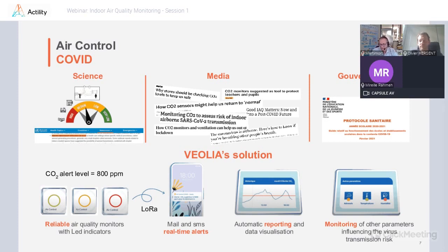So for the position of the CO2 sensor in a room, it depends on different parameters. The objective of this measurement is to represent the presence of the occupant. So if we have 1, 2, or 10 persons in the room, this CO2 can detect, not directly the number, but the CO2 level in the breathing zone. The breathing zone should be determined where the occupant stays the most in this place. And it is also dependent on the airflow rate and the air distribution in the room.